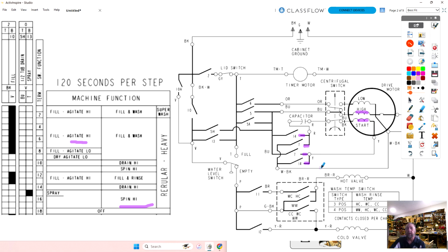So on this particular unit, if I want to go one way, I go to 7 or 14. I'm telling you, the motor works in agitation, but does not work in spin. What part do I replace? You do not need to test anything with a meter. We have disconnected the motor from the transmission and pump to make sure that neither one of them were binding it up so it wouldn't run, and it was turning freely. But in agitation, the motor ran fine, no problem, no smoke, no burning smell. You put it in spin, and the motor just hums. Is it the clutch?